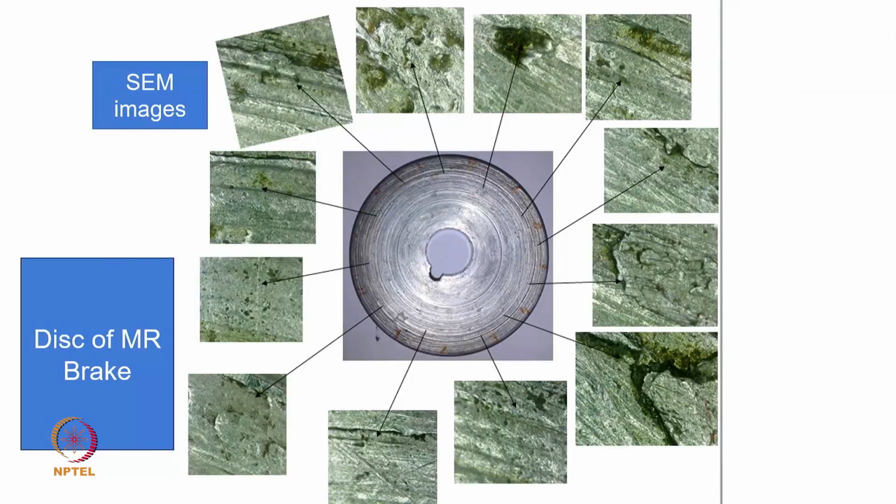We can also look at the material. We know very well that a brittle material will not sustain a 90 degree impact, while a ductile material will get cut at the lower angle. These are different materials with different characteristics. So if we are able to observe the debris or material composition, we can think about the wear mechanism, the failure mechanism or the fracture mechanism. Of course, the question will come again and again: how am I connecting wear with fracture? Maybe in the next few slides I will try to cover that.